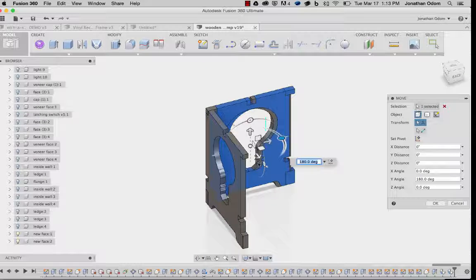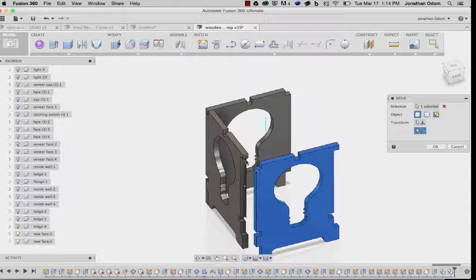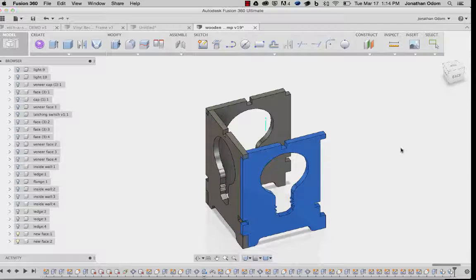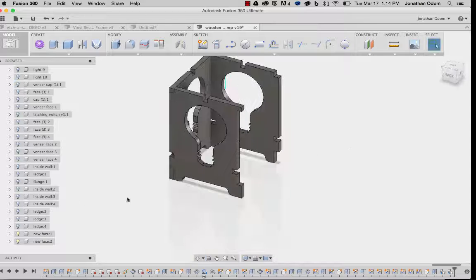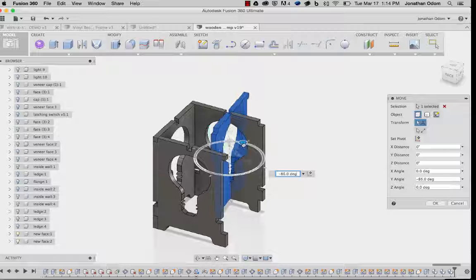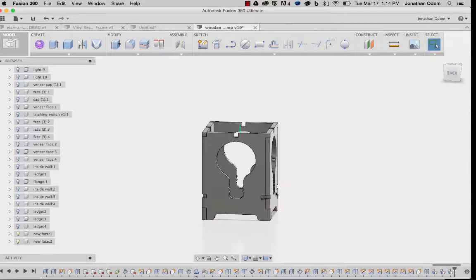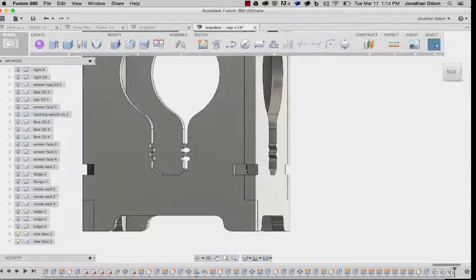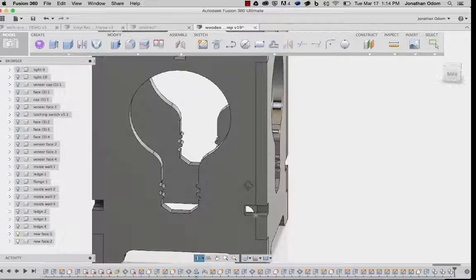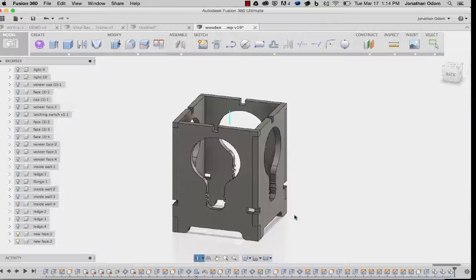So I'm just kind of moving this around until it's in the right place. I can move from point to point here. You could also use joints in this case, but there's really no need. Just going to paste again, rotate it this way, and do a point to point move here. So you can see how they interlock, and then here, this little recess is for an extra part that's going to hold a trim on the bottom that holds the LED assembly.